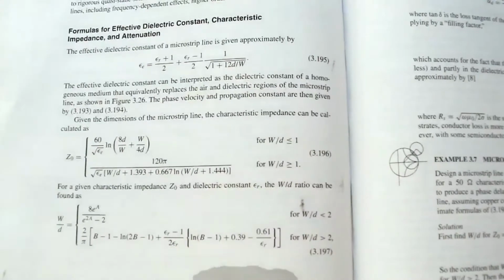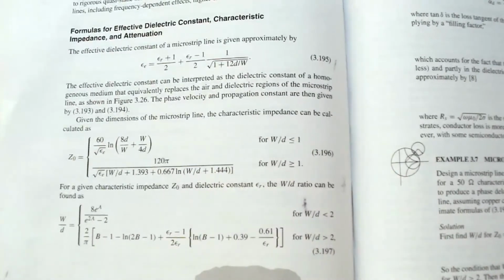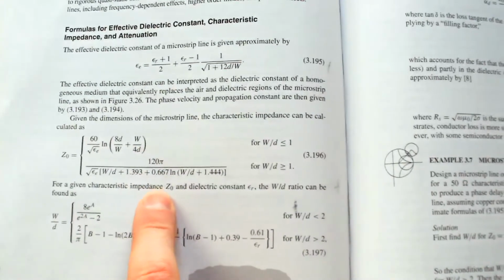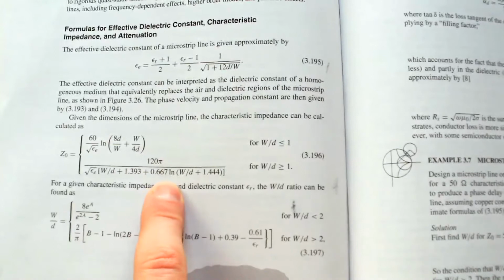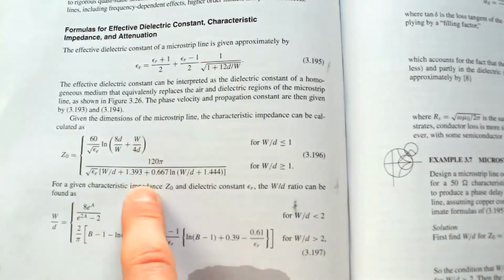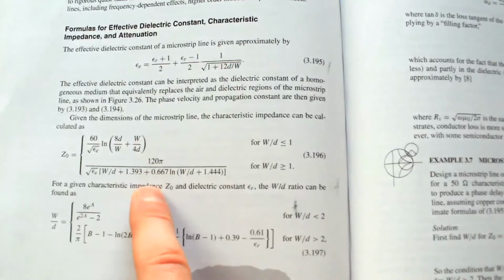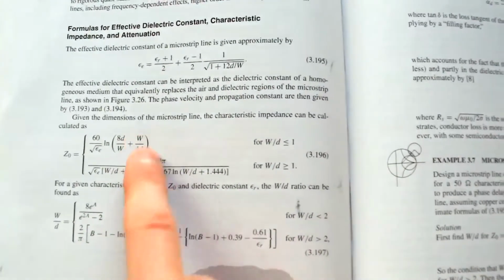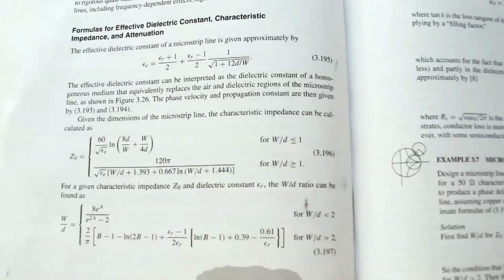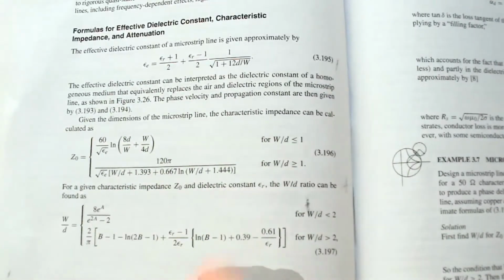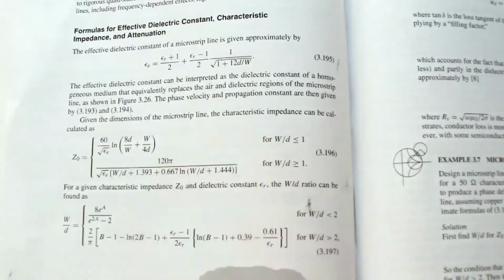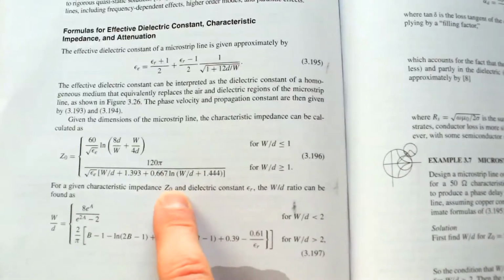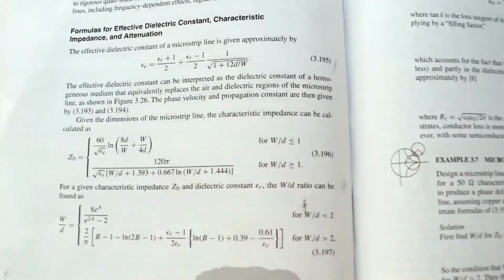So it looks worse than it is, because you can just stick this in MATLAB and it'll crunch on it immediately. All you have to accept is that there's a tiny bit of error in these expressions. They're approximate curve fits that closely follow the numerical values they got. So they won't be exact, but they'll be pretty close. They're good ballpark figures. If you want exact, you've got to simulate it. But these are a good back of the envelope way of figuring out your impedance based on the geometry.